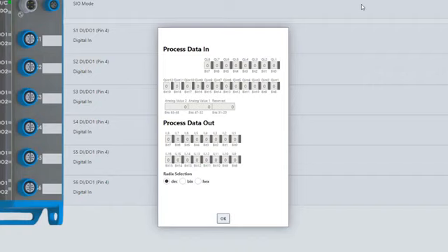button view. When the digital process data out mode is selected, the SIG100 process data out will receive up to 16 discrete values from the IO-Link master. These are labeled IL1 through IL16 and will appear for use in the logic editor.